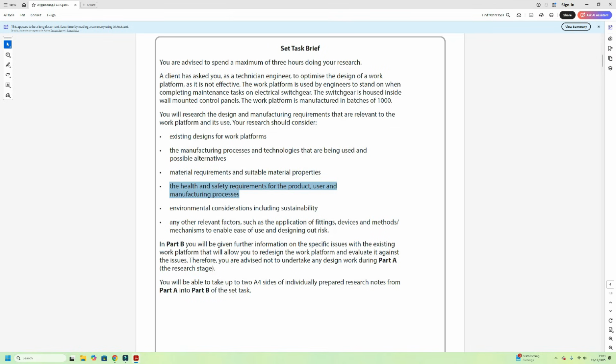If you're using laser cutters, you have to protect their eyes, and obviously you have to extract the fumes. If you're using plasma or oxyacetylene, again, you've got to be careful of the heat, also the fumes that come off it. If you're wet spraying or powder coat painting, you now need to think again about extraction of the fumes and catching the paint. We don't want the powder going off into the atmosphere. You want to capture that, so there'll be some filters and bits and bobs that hold on to that.